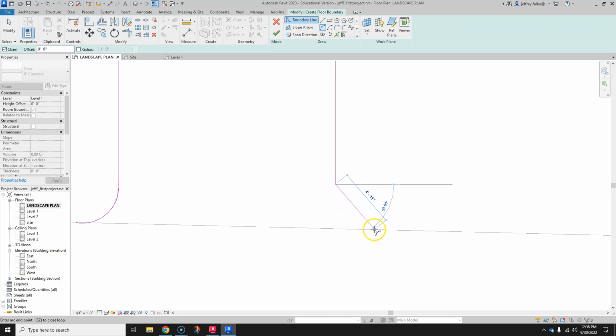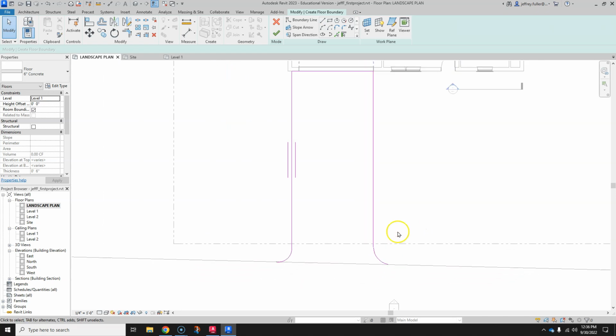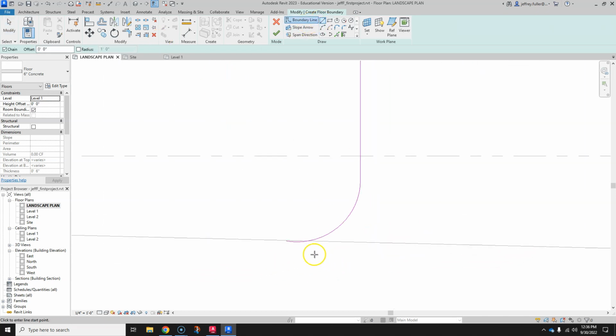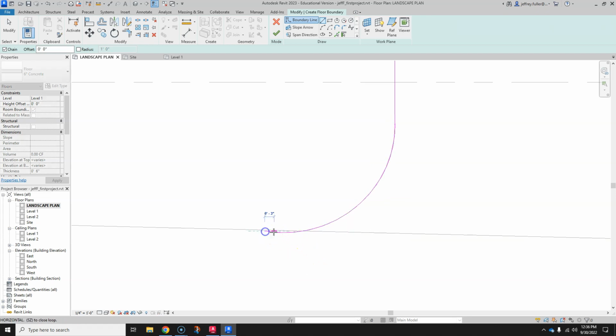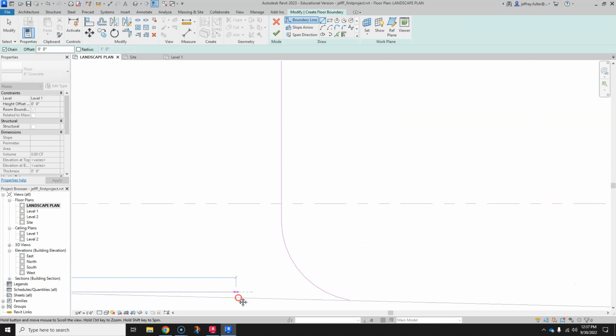So sometimes they are going to be slightly different in value as far as the radius is concerned. All right, oh yeah, we got to close the end down here. And when you do this, you got to be careful. If I draw this line straight, look, it just goes right across that arced line, which is going to really screw me up. Okay, so just kind of come out a little bit and then go across. That's all you got to do. It's no big deal.